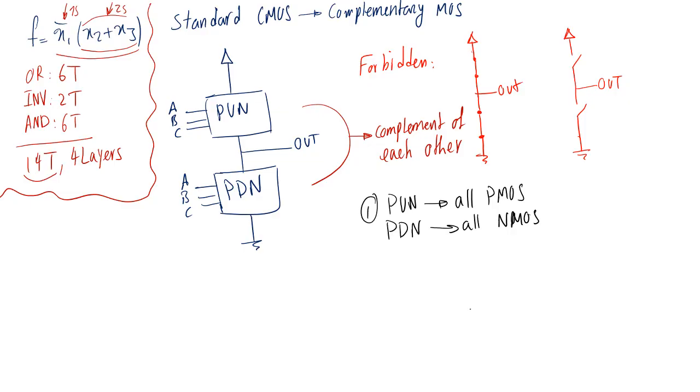It was mainly because PMOSs are generally better at connecting things to VDD, and NMOSs are better at connecting things to ground. The reason for that really comes from the physics of transistors, and I would have to explain a little bit about the relationship between the gate-source voltage and the threshold voltage. It's beyond the scope of this course. Just remember that one of the rules for standard CMOS design is that in the pull-up network you should only have PMOS transistors, and in the pull-down network you should only have NMOS transistors.